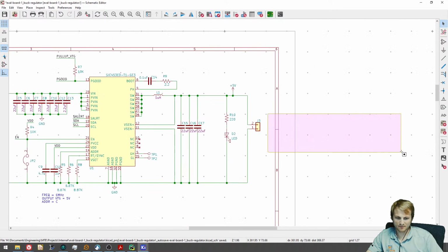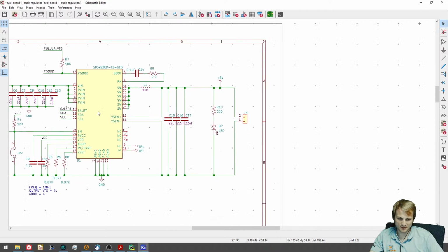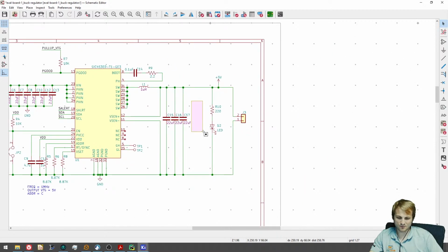If whatever you're powering out here has really big transients, where steady state is say 5 amps and then it ramps up to 10 or 15 amps quickly, that can absolutely sag this entire rail down, and then you're going to be forced to grab it all on the input side. That's when you would want some bulk capacitors.